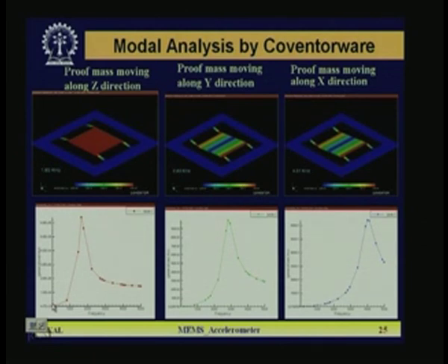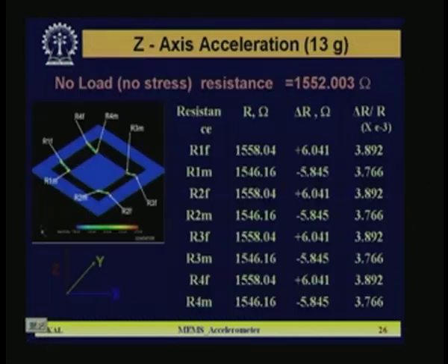And here in a similar way we did the modal analysis. In the modal analysis I found that 1.65 kilohertz is the resonance frequency, the second is 2.83, and here is 4.01. So there is not much change in the modal analysis because of the movement of the flexure.